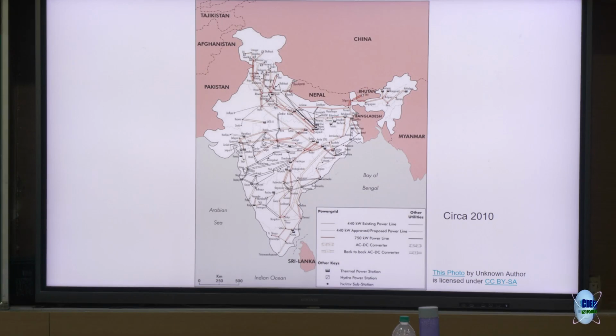If you see the north part, for example, or the northeastern part may have substantial hydro. The southern part may not have hydro. The southern part had a lot of wind. Other parts may not have so much wind. If you talk about today's context, then there is a lot of solar in Rajasthan and Maharashtra and MP probably. Other parts may not have it. And not just load, these sources also have their characteristics. At different times of the day, they will have different power. Solar will have more power during the day, wind can have different characteristics. So it's always good to keep connecting, so that anytime one region needs power, and there's excess power elsewhere, you can give it. So these interconnections always help.